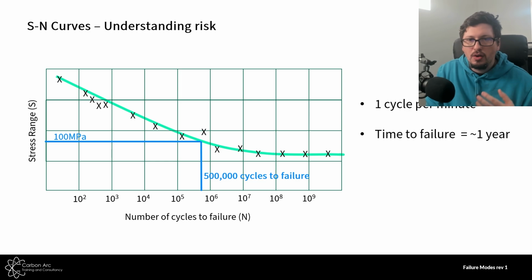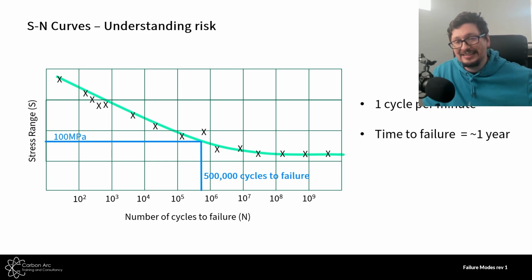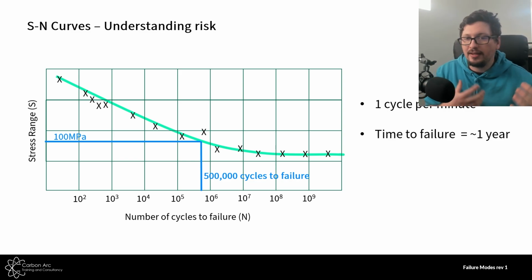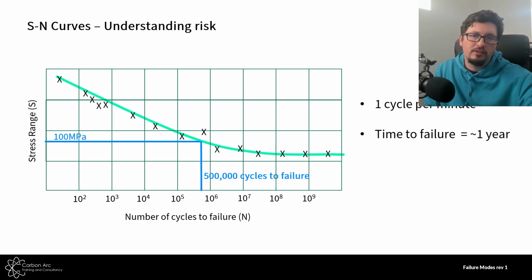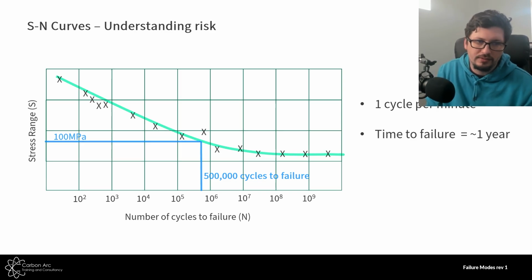Now, in most cases, we have already existing standards that allow us to access them and use their SN curves to work on. DNV have one, C203, and you can go through and put your data in and get your expected life. But by maintaining quality of welds, this is what we're helping to improve is the fatigue life of our samples.